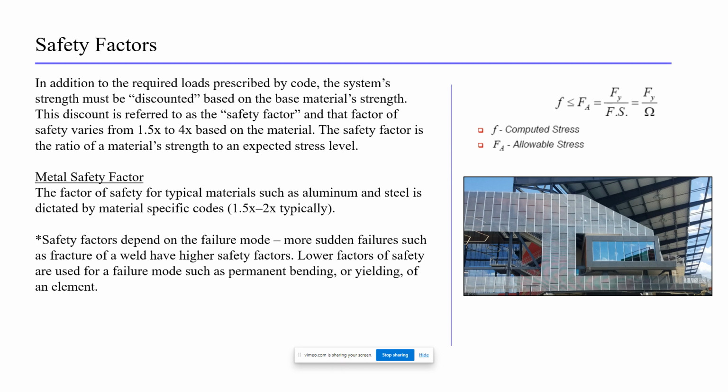So design teams should also understand and be able to distinguish between testing and engineered design. They get occasionally confused with one another. Factors of safety are relevant only to engineered design, not testing. In other words, for all demountable systems, including railing, testing involves applying a discrete load to the system in the laboratory or in the field.